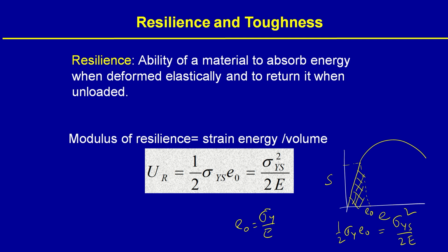That is, to be specific, metallic glass is used in the golf bat, because metallic glass has a very high yield strength. It can have a yield strength of 3 to 4 GPa. You probably may not have heard it, but very high yield strength is possible in those materials. It has very low ductility, but that does not matter, because here the material is not going to deform plastically for the golf bat.